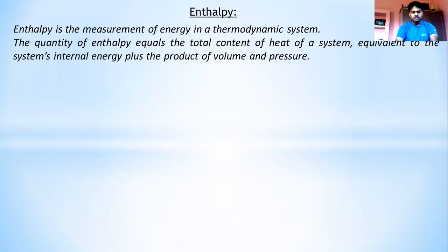Ideal gas expansion in isothermal mode, what will happen? The value of internal energy depends upon temperature. At constant temperature, the change in internal energy equals 0. So del U equals Q plus W, and as del U equals 0, 0 equals Q plus W. Q equals minus W, so minus Q equals W. So these are the applications of the first law for different thermodynamic processes.